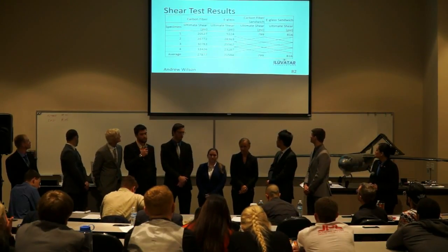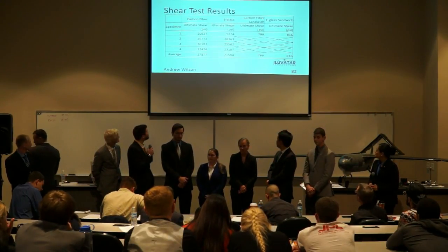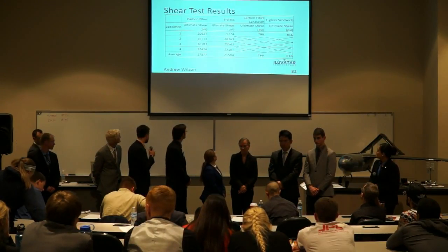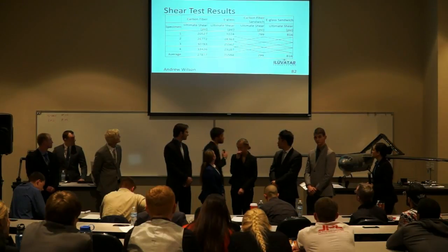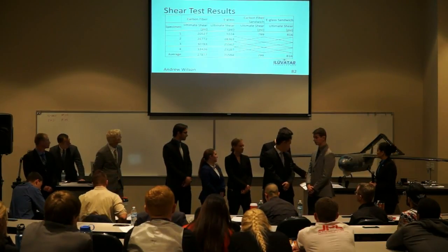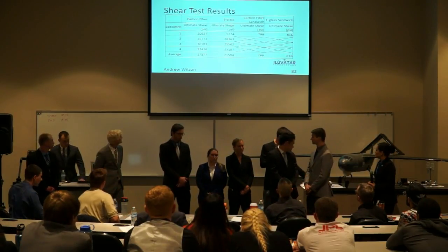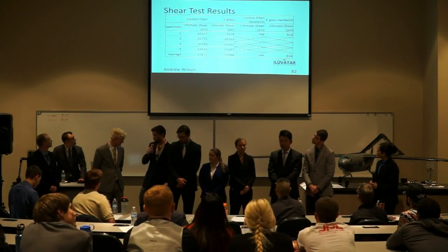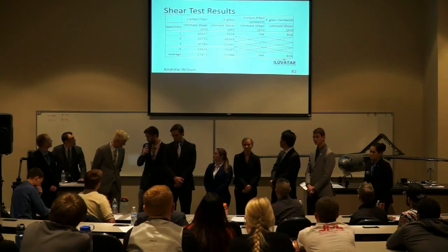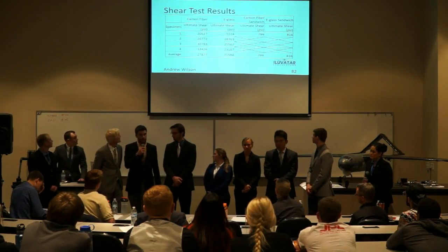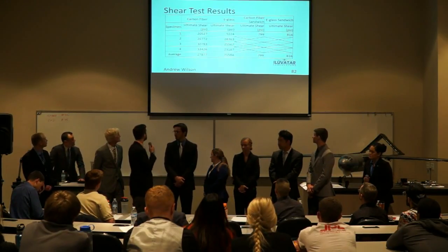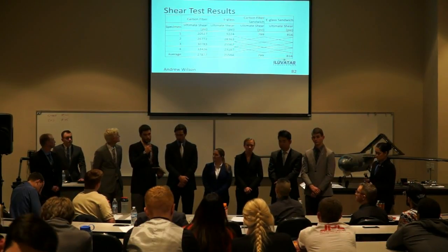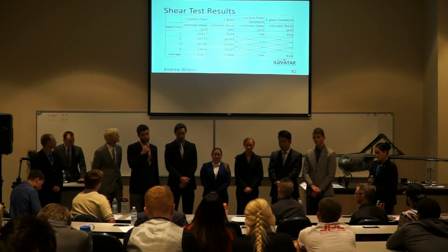And just looking at your E-glass, your first specimen gets right around 9,200 PSI, and then your specimen 4 is 2,300 PSI. That's a pretty significant range difference, and yet you still keep those in your average to say these are what our test panels are going to be. So how do you guys make that determination that your values can be used to size your model?